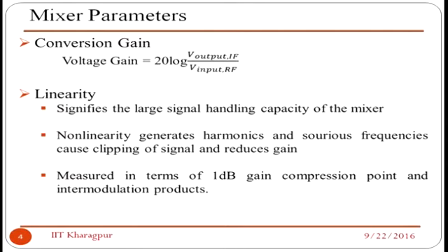Why? Because this omega LO minus omega RF I want, but it will also come with all its siblings, its harmonics, intermodulation products, all kinds of subharmonic series, and that will reduce your fundamental or the desired output signal amplitude. So spectral purity, how pure it is, is an essential part.